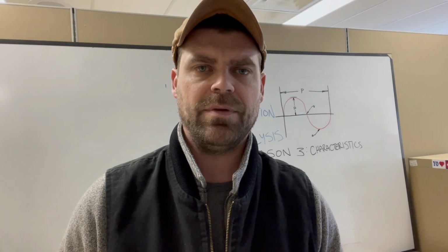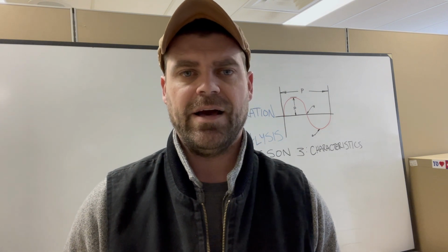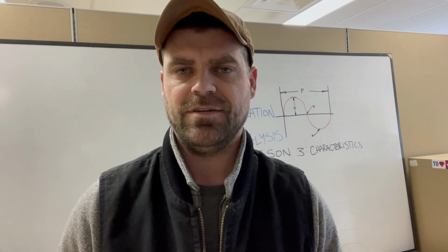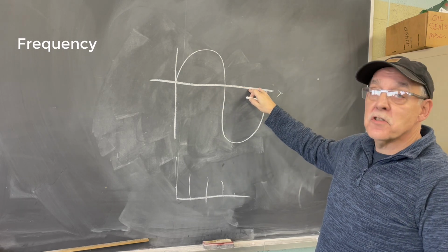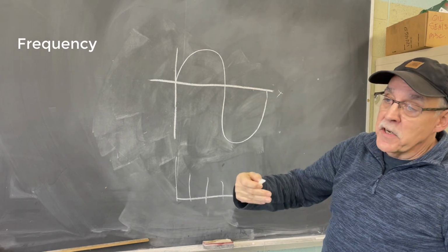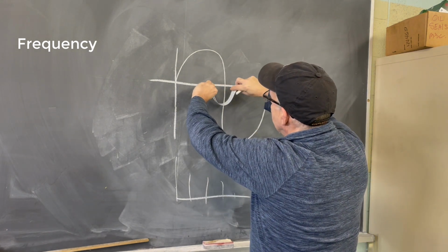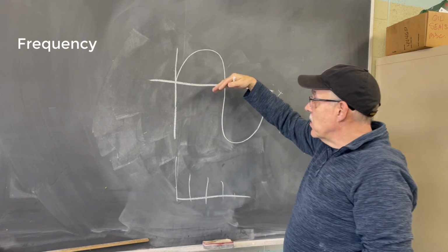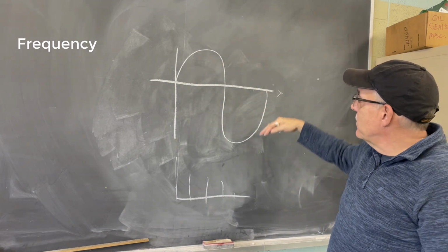There are a lot of time-based terms in vibration analysis, like period, frequency, cycles per second, cycles per minute. Let's get Paul to explain how these all relate to the vibration analysis that takes place. So this axis here in the sine wave represents the neutral position. Definition for vibration is back and forth from its position of rest. So there's our back and forth movement, one complete turn, one cycle of vibration.